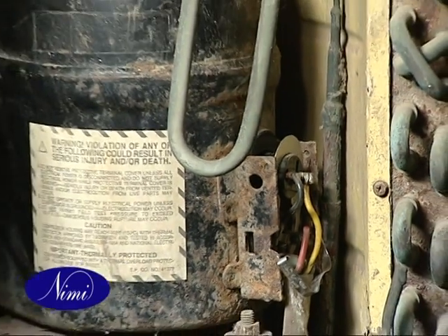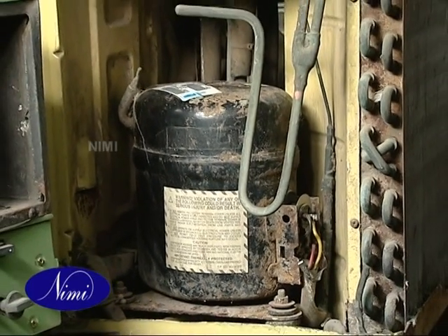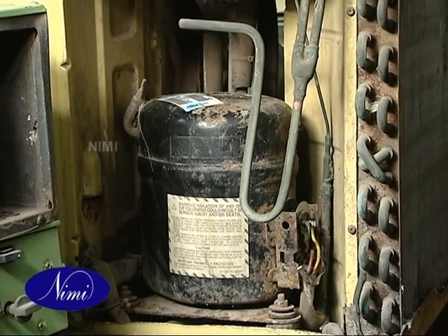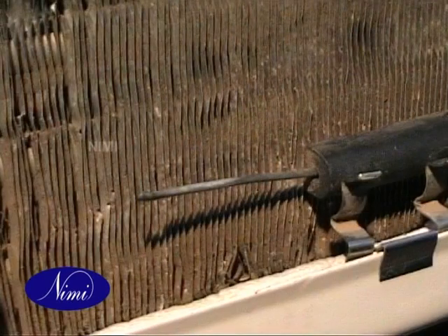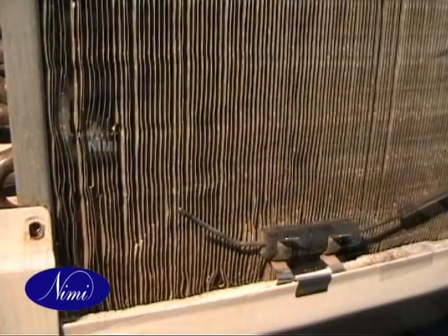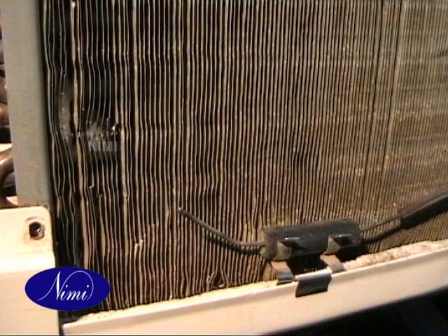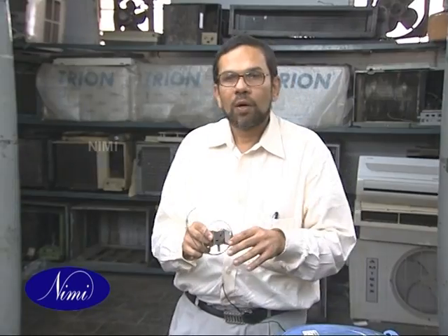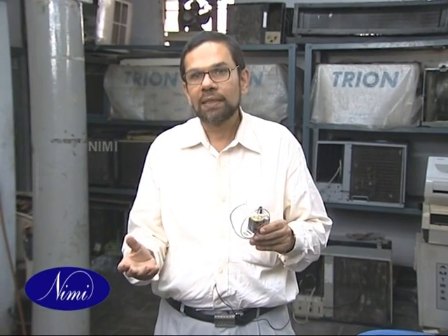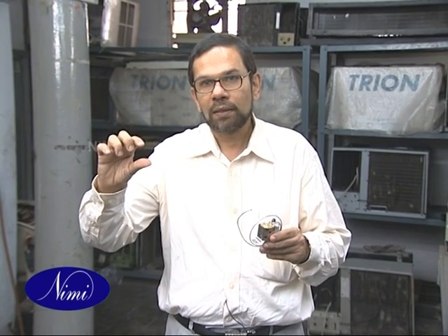Once the compressor is switched off, there is no cooling, so the temperature goes up again. As the warmer air is drawn over this bulb, the temperature goes higher and the signal is sent again and the compressor switches on. Of course, the main function is regulating the temperature between a particular fixed point.